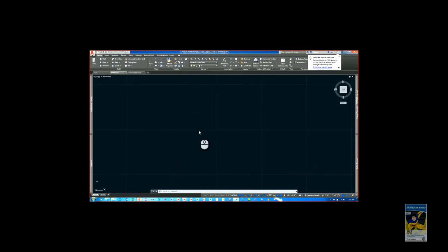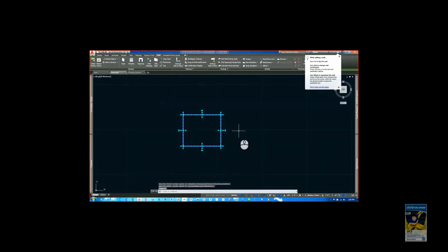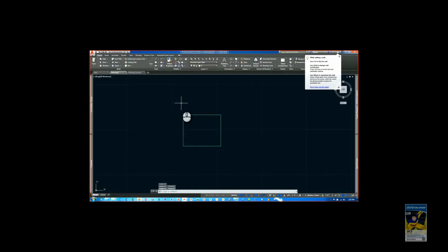And the last new feature in Autodesk AutoCAD Architecture 2017 is the ability to create shapes when you're working with certain objects. For example, if I start the wall command, if you look down here in the command line, there is a create type feature here that if I click, I can actually choose rectangular, circle, polygon, or P-line. So let's say I pick rectangular. I can just draw a rectangular shape and it automatically allows me to draw that shape using the AEC objects. And that's for walls. Hit escape twice to get out of that.